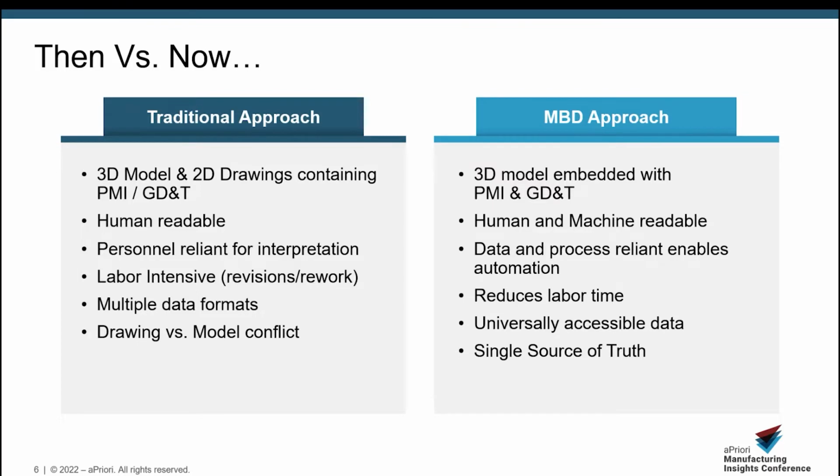So as we move towards MBD adoption, what does that do for engineers and their workflows? Most of us are familiar with the traditional approach of designing a 3D CAD model, and then we go through the tedious, laborious, and labor-intensive process of creating two-dimensional detailed drawings in which we then release. We do this to bring our product information into a human-readable format, which oftentimes leads to misinterpretation and rework. So with the MBD approach, 2D drawings are essentially eliminated. This is done by generating a 3D CAD model with MBD that puts all the relevant product information and full product definition into a machine-readable format, which can then be consumed by other tools in the digital workflow, such as aPriori. So MBD drives the model as the single source of truth and eliminates the drawing versus model conflict that often exists in manufacturing workflows.